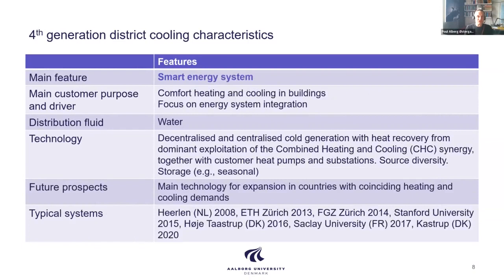Moving on to fourth generation district cooling, and now we are into something we are still developing. It is installed in some places, but here the focus is very much on smart energy system integration. I did mention that when you're producing heating with the heat pump, you're producing cooling also, so there's a synergy there. But here it's more or less 100% based on that synergy. Very much on that part. Also some natural cooling if you have that. And again, it's a matter of sending cold water out to customers. So you take the complexity of most of the installations away from the customers.